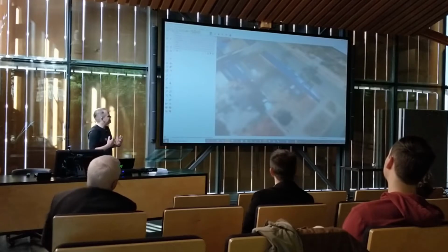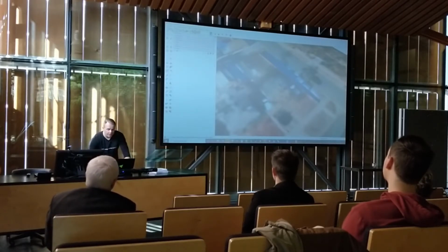Now this is not exceptionally usable, but my friend Daniel Tall put together a plugin called Placemaker. So I'm going to open up Placemaker. I'm going to select this aerial imagery and then click on Placemaker, and let's go ahead and download our Nearmap imagery. I've got the aerial imagery selected. I chose Nearmap as my source, and I click on imagery. Now this is going to take 4 credits. I'll click download, and watch how much better this gets.